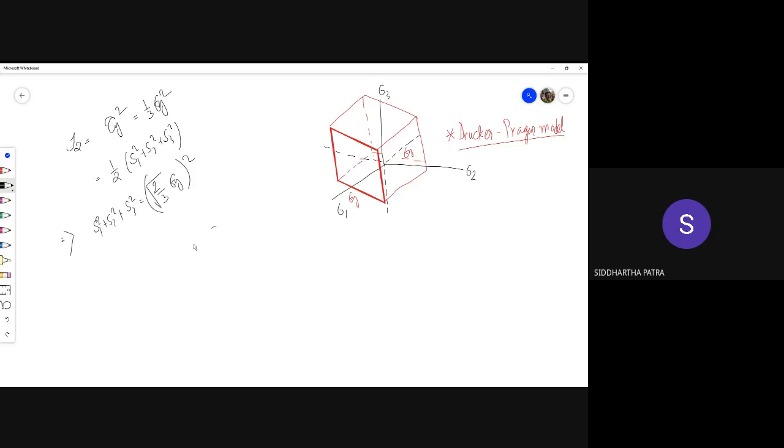As we have explained earlier, sigma 1, sigma 2, and sigma 3. So imagine this is the plane, the deviatoric plane, the octahedral plane that has the same intercept with the three axes, same intercept value. Now just look at the center of it, and this is the axis that goes through the centroid of the triangle. This is the hydrostatic axis. This axis can be represented like this: 1 by root 3, 1 by root 3, 1 by root 3.